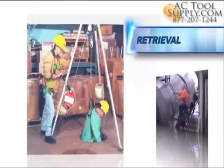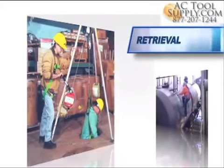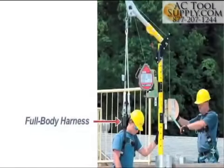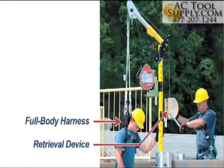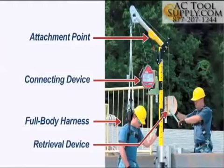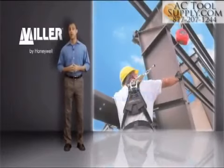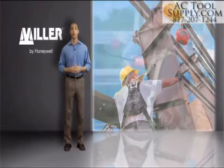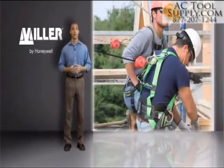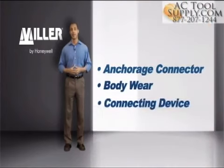Retrieval systems are used in storage tanks, manholes, and other confined space applications. The system includes a full body harness, a retrieval device, a connecting device, and an attachment point such as a tripod or DuraHoist system. The three key components of the personal fall arrest system must be in place and properly used to provide maximum worker protection: anchorage connector, body wear, and connecting device.